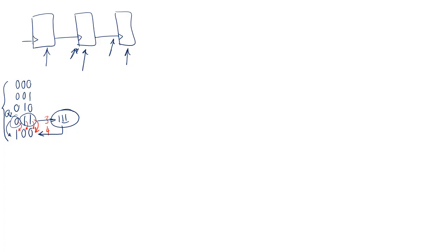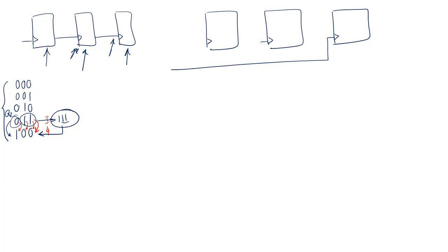The way I design this counter is that I still use 3 toggle flip-flops because, well, it's a 3-bit number, so probably I don't need more than that. But I connect the clock signal of all of them to the same thing, so the positive edge of all of them happen exactly at the same time, so they're fully synchronized.